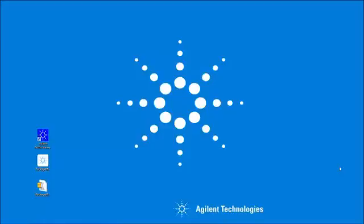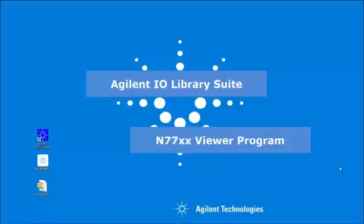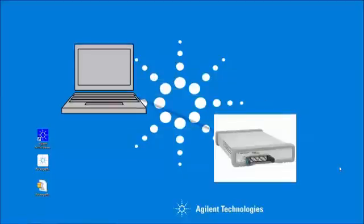And so now that you've downloaded and installed both the Agilent I/O Library Suite and the N77xx Viewer program, we can establish a link between the power meter and the PC. So go ahead and turn on the power meter, connect a USB cable between the power meter and the PC, and we can open up a utility called the Agilent Connection Expert.